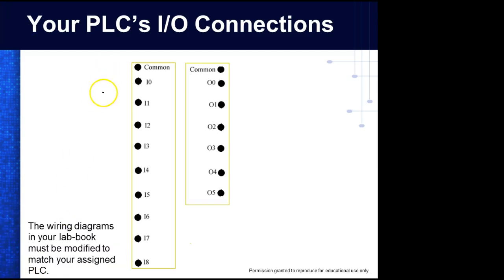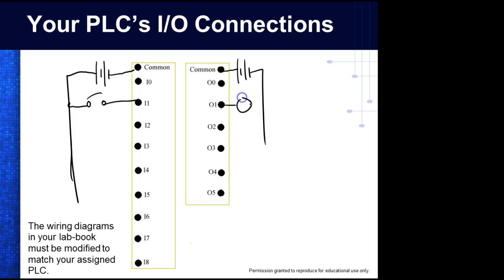So I'm going to put my DC voltage source up here. And I'm going to point the minus toward the common. Right? Understand? And then I'm going to come over here and run a rail down here. And then I'm going to do what? Then I'm going to connect my inputs over here. Now we're using a sourcing output, and then we'll connect our output devices over here. Okay?